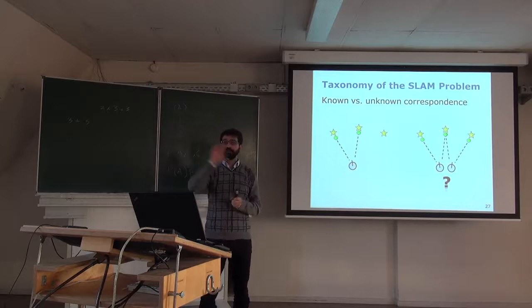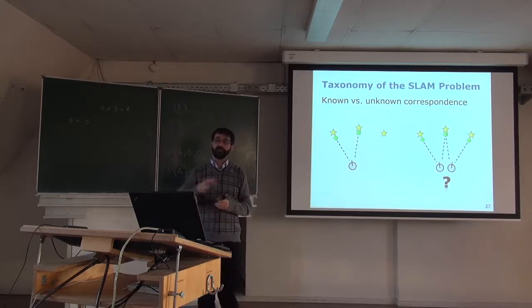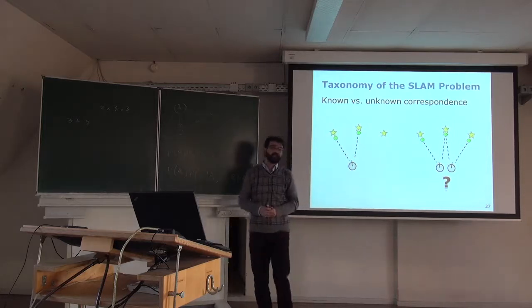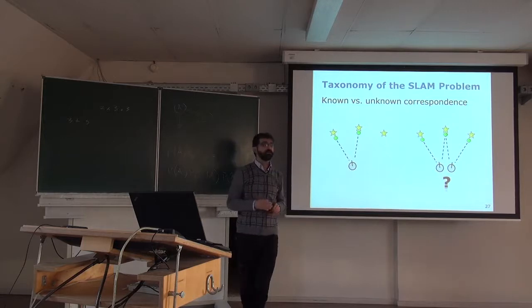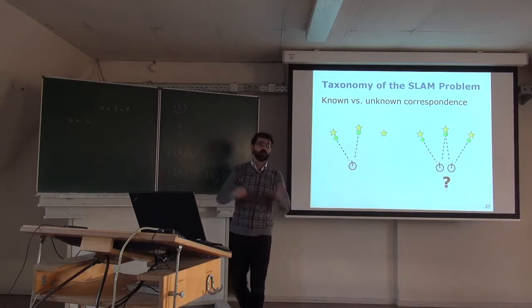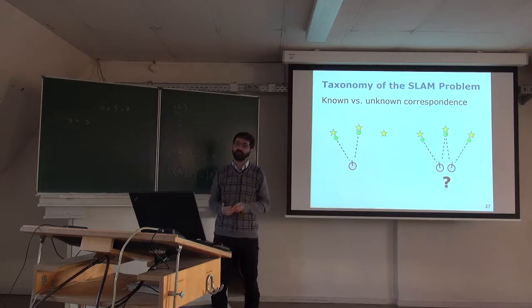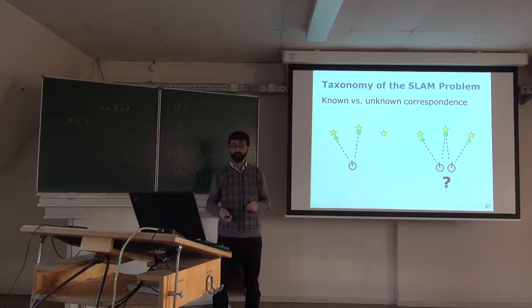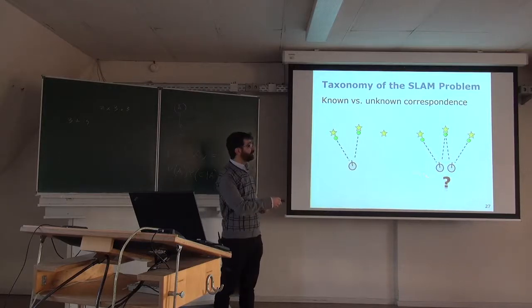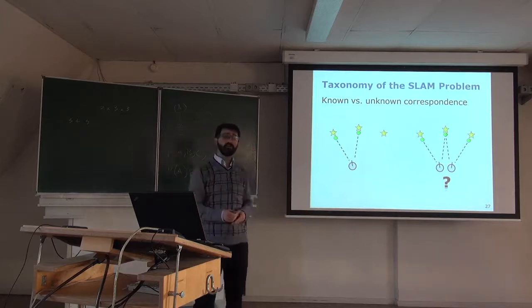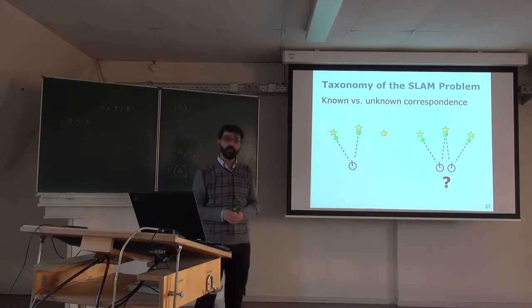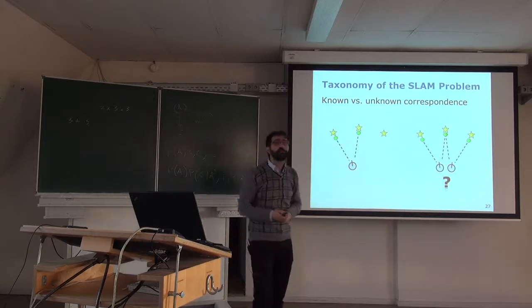That you can have ambiguity, but if you eliminate ambiguity from the beginning, you say, these are IDs, they can be whatever, QR codes that you can recognize with the camera, or they can be barcodes or something which is uniquely identified in the environment, then you know for sure the correspondences and the problem gets easier. If you don't, then you have an additional problem on top, which is the data association problem, and you need to be able to distinguish if these two landmarks are these two stars or these two stars here. Okay? Again, a different level of complexity.